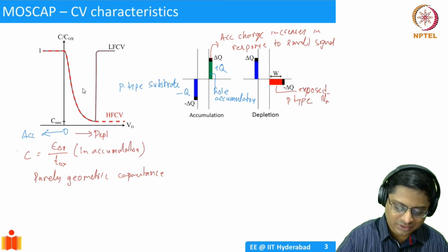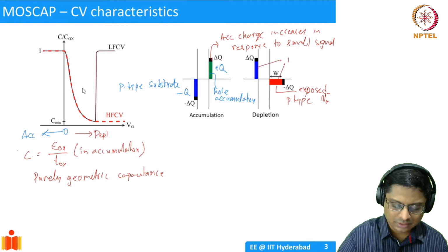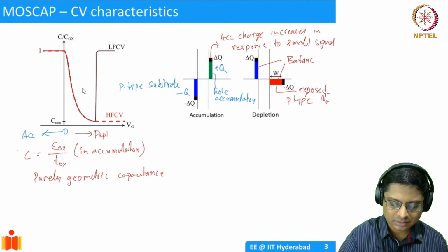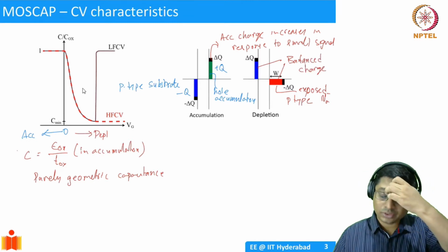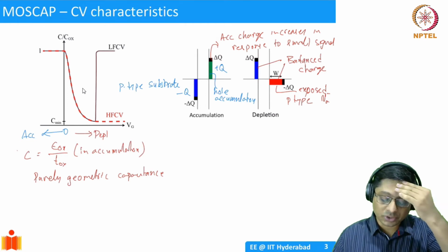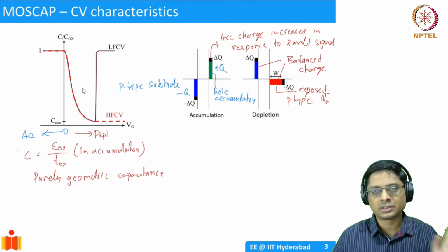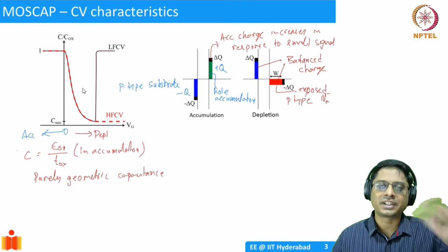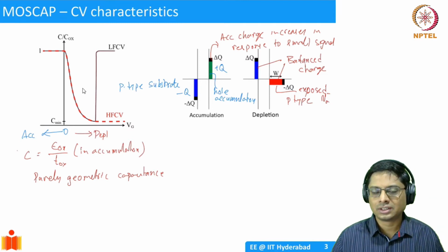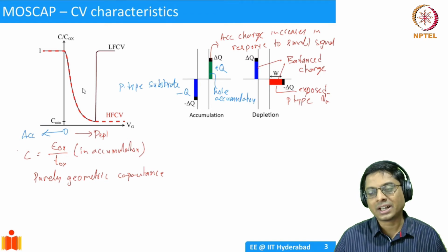So basically this balanced charges. So the electrons on the metal has positive charge now, and that will be balanced by the negative charge created by the depletion region. Now if you add a tiny delta Q on the metal, the minus delta Q is going to come from the edge of the depletion region.